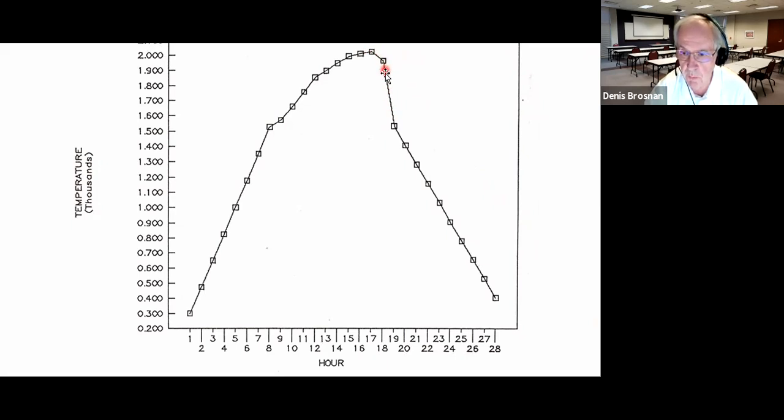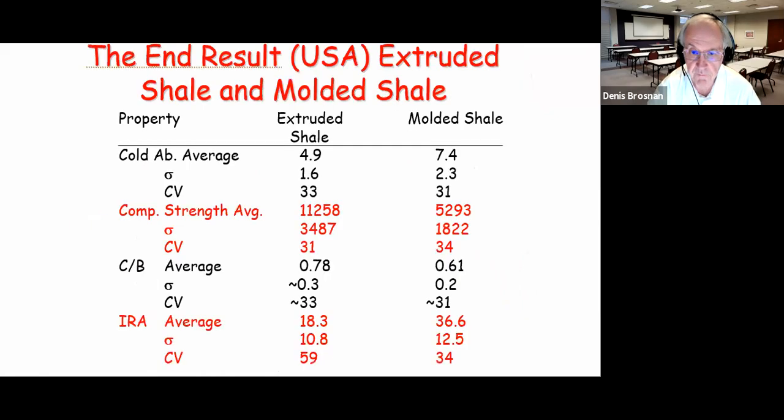They call the bricks pyroplastic, meaning they will deform easily at those high temperatures, but they get down here in this realm of, in this case, about 1500 degrees Fahrenheit, and they cool more slowly in this area right here. Sometimes we'll see them even cool more slowly as we go from beta to alpha quartz, or certainly if there was cristobalite, then they cool more slowly down in this area.